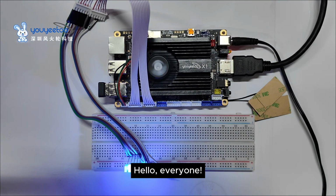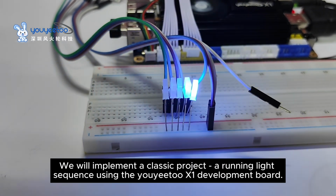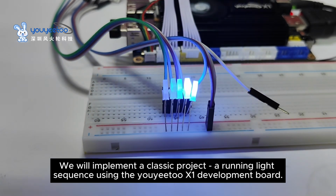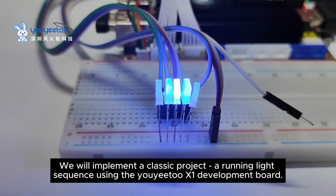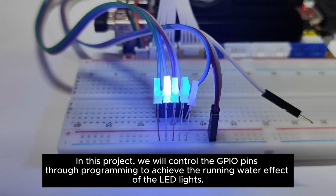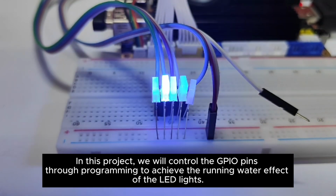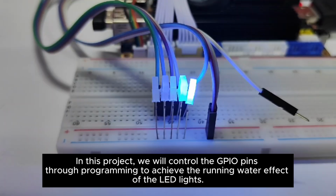Hello, everyone. We will implement a classic project: a running light sequence using the Youyeetoo X1 development board. In this project, we will control the GPIO pins through programming to achieve the running water effect of the LED lights.